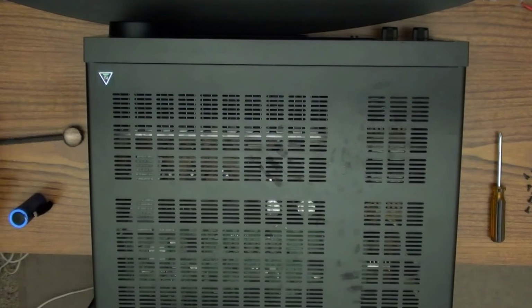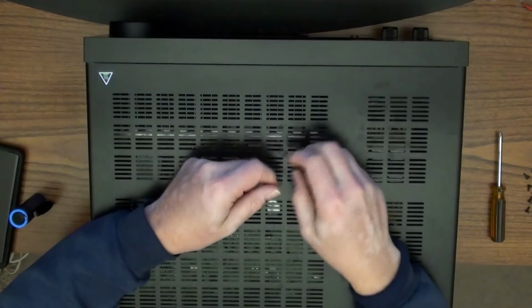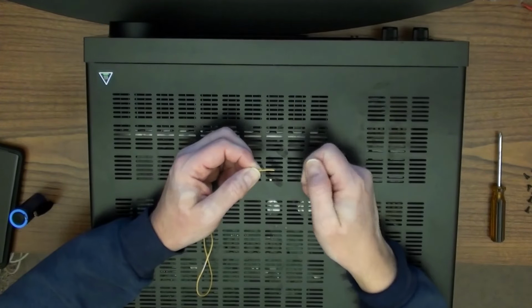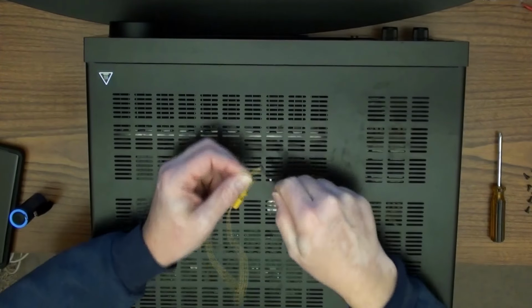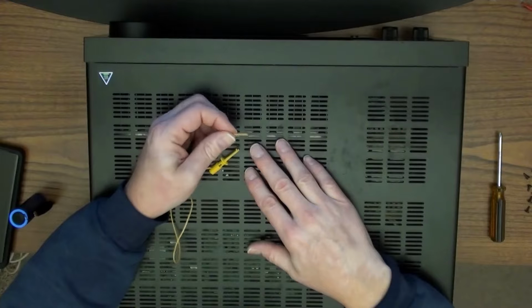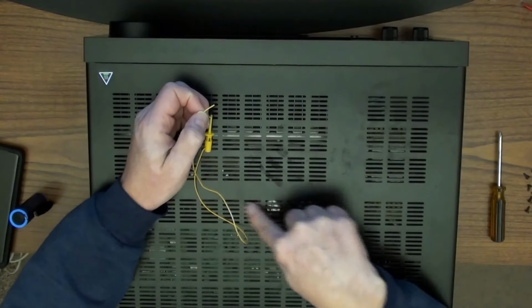Alright, I got this apart, and before I touched anything on the inside, I had a look around, and I just want to point out one thing about connecting things to amps, mainly the speakers. When you peel off the insulation on the speaker wire and twist it so you can stick it into the back connection, don't do it over the amp, because the wires that break off in the process are going to fall between these holes, guaranteed.